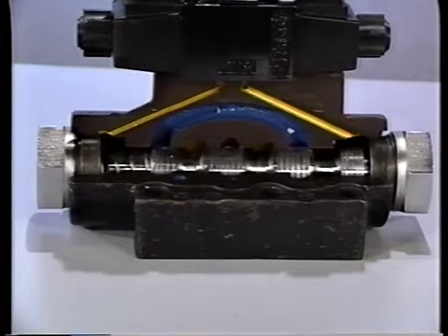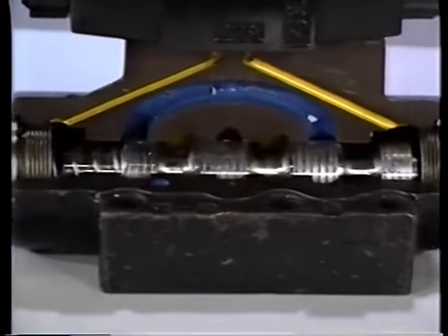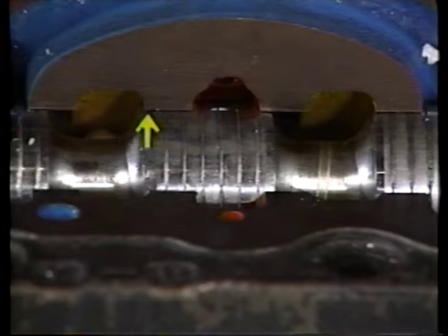Other valves we have seen generally permit more leakage than check valves because there are no seals between the various ports. The close fit between the mating surfaces is all that prevents the passage of fluid. And in many cases, some leakage is actually required for proper lubrication of the valve as it operates.